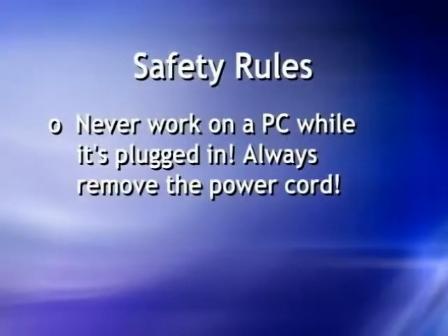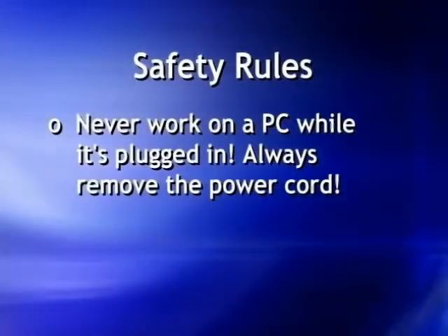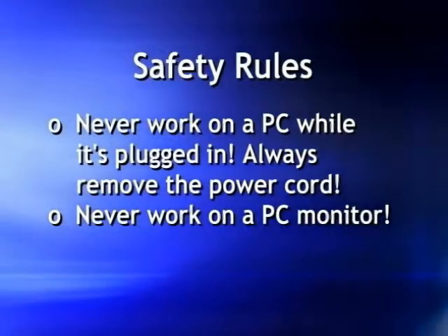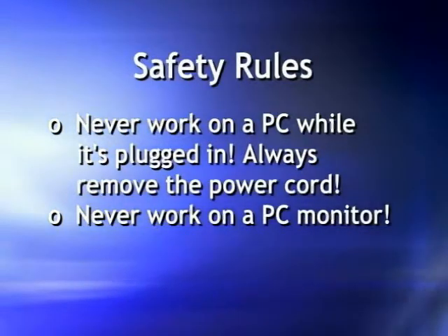Now there's another issue you need to be aware of, and that is never, never, never open up a PC monitor and try to work on anything, okay? Here's the reason why. Inside of a PC monitor, there are components that store electricity, and we're talking about tons of it. We're talking about 20,000 volts of power.